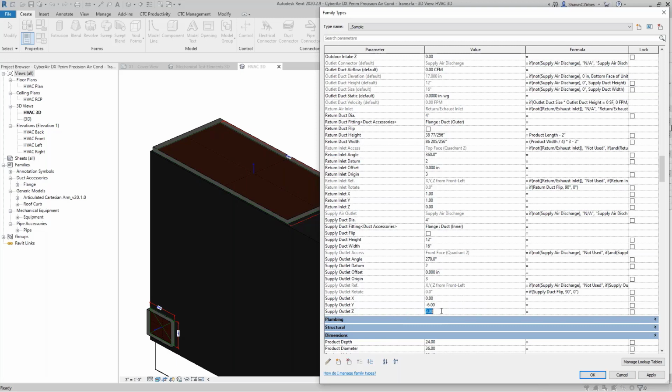My position here is going to be 1 inch off that bottom left corner on the Z direction, vertically off that corner, and then 1 on the X direction as well. The Y doesn't make any difference because it's sitting out here on the face. There's no offset. So for visual purposes, so I don't confuse myself in the future, I could set the Y to a 0 because it's not doing anything anyway at this point. Hit apply, that connector goes to the right spot. And then all I have to worry about is the height and the width of this. Just going to modify these numbers.